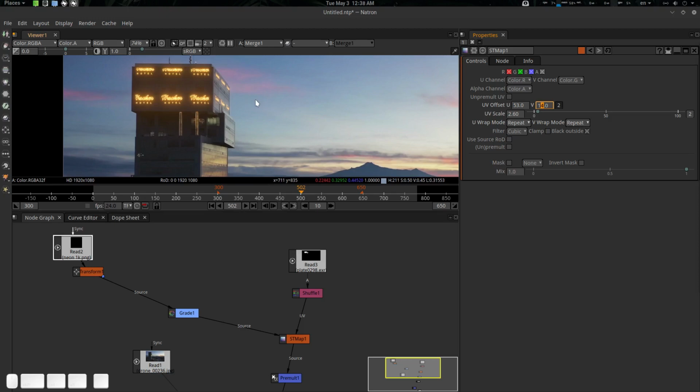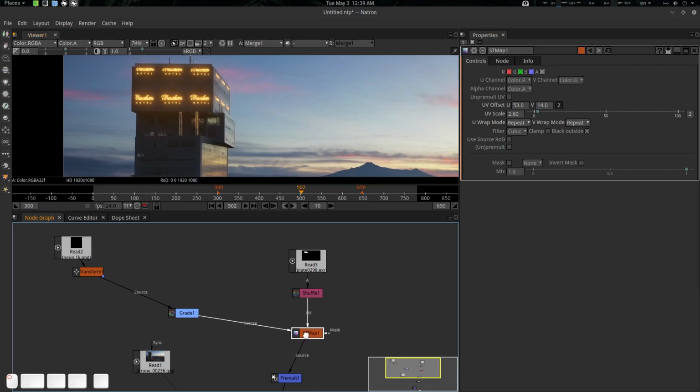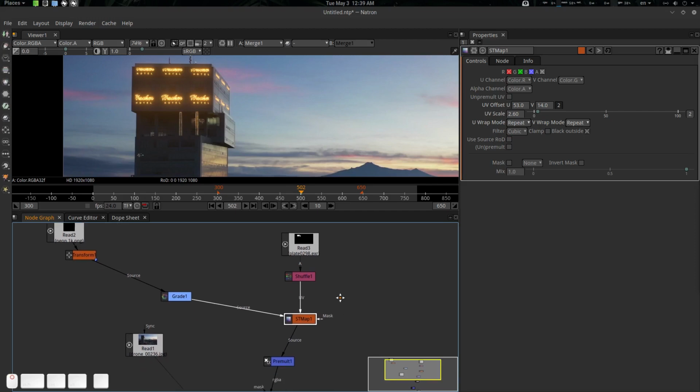It is useful because we can render our basic textures and everything, and we can use this STMap to create texture generation. We can directly change our textures and everything. It is also useful for camera projection, which we will see next, and it is actually useful to create UV paths and manipulate them. You can also use it for reflection, fake reflection. You can also use it for refraction. You can also use it for UV distortion. We can also use it for texture deformation. So lots of applications are there for this STMap alone. So it is very much useful. It's a very useful node and technique.